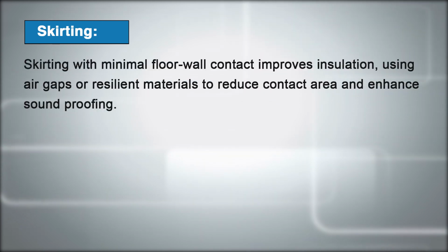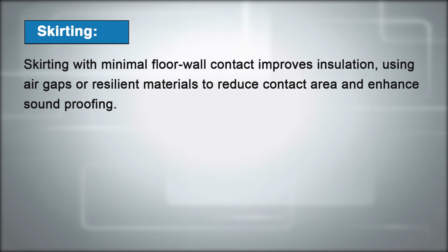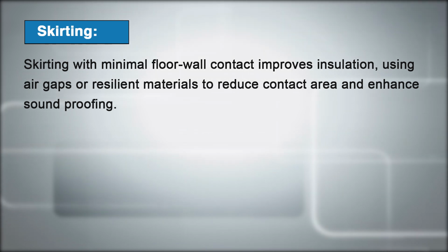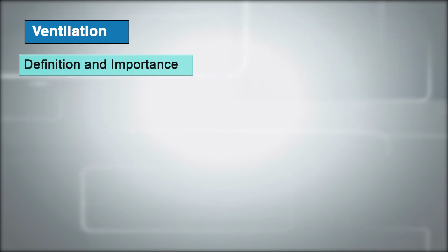Next is skirting. Skirting with minimal floor-wall contact improves insulation, using air gaps or resilient material to reduce contact area and enhance soundproofing.